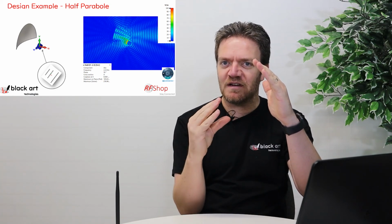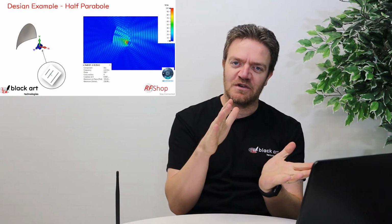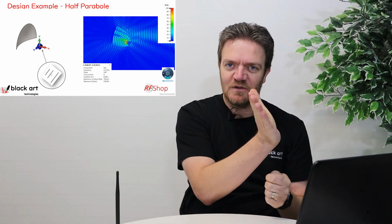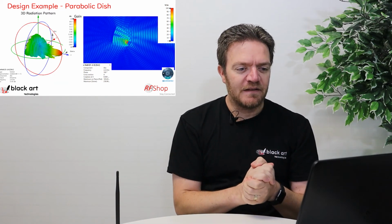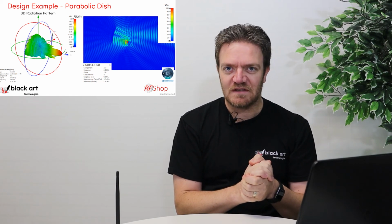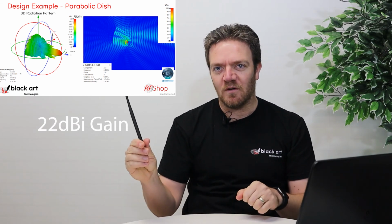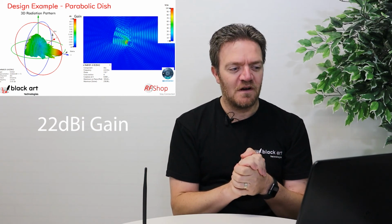You do have to manipulate the orientation a bit, because it's pointless for an antenna that's first here to just send to the bottom. So you do tilt it a little bit, and that's what I show in my picture there, that it is tilted a little bit towards what's left of my original dish, and you still get the same idea that the field transmits into this surface. The surface reflects it forward, and what I lost from what I had before was 26 dB. I have 22 dB, but again, I'm not going to complain. There's a 2 dB dipole converted into an overall system that now gives me 22 dB in the forward direction.